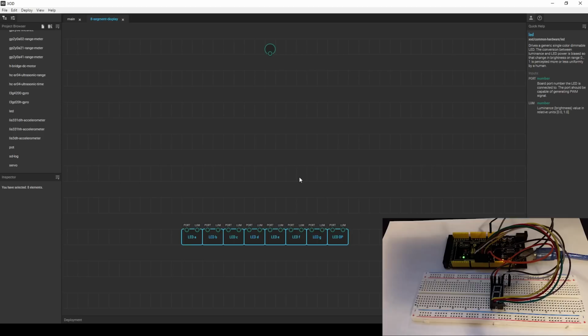I would normally just load in all the ones and zeros in an array and then have it compare the input to what number the array is at and just dump that into a buffer and then send them to the LEDs. This is going to actually compute each segment, what needs to be lit for it. And you'll see what that means.